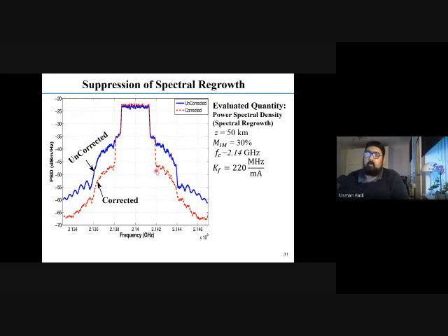And it is more visually clear that over here, the blue curve, which is the output without DPD, has higher spectral regrowth. And with this technique that we have developed, you're able to suppress the regrowths and the leakages in the adjacent channels. So we are good, and we can see that we have a good improvement here.